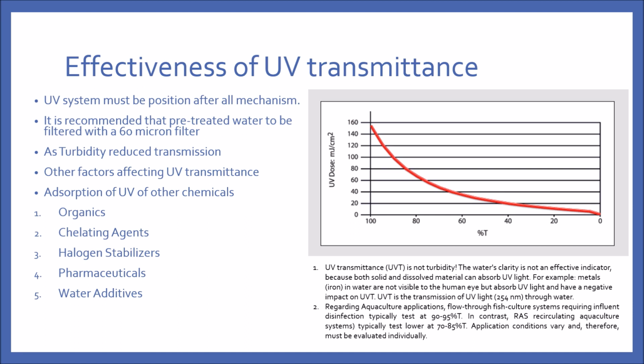For example, if your suspended solid removal control is not done well, you will have a lot of fine particles floating around the water. Now, imagine your UV light trying to disinfect the water. But since your water is filled with suspended solids, it is not likely the light from the UV source can reach the pathogen, resulting in a widespread of pathogens in the system and your UV light useless. That is one form of reducing transmittance via turbidity. Sometimes there are other methods. For example, excessive organics in the water would also decrease the UV transmittance.